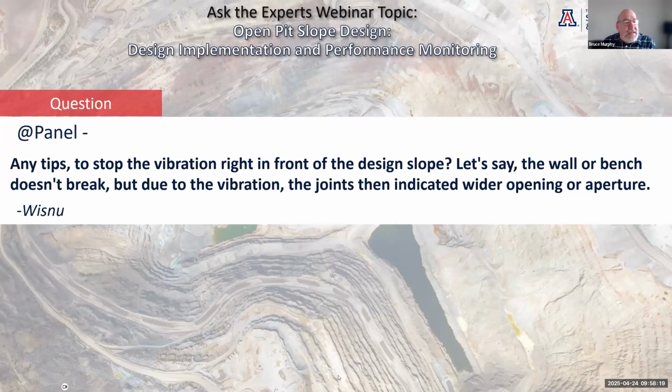The other thing that's happening is there's a lot of tight cuts. People are trying to do center lift blasting and all that kind of thing. We need to do the monitoring, and we need to put seismographs on the block and on the slope and get a feel for those PPVs and frequencies and understand those things quite classically.